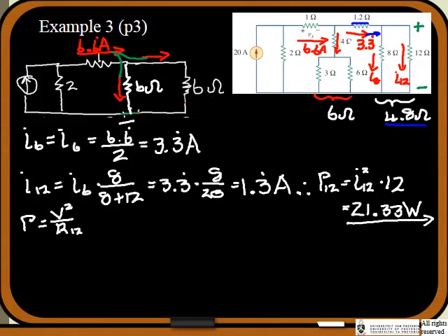So what is the voltage that we're looking for? V equals 3.3 repeating multiplied by that resistance, which is 4.8. Let me grab my calculator here. 4.8 times 3.33333, and wow, that's a very nice number actually. It works out as 16 volts.